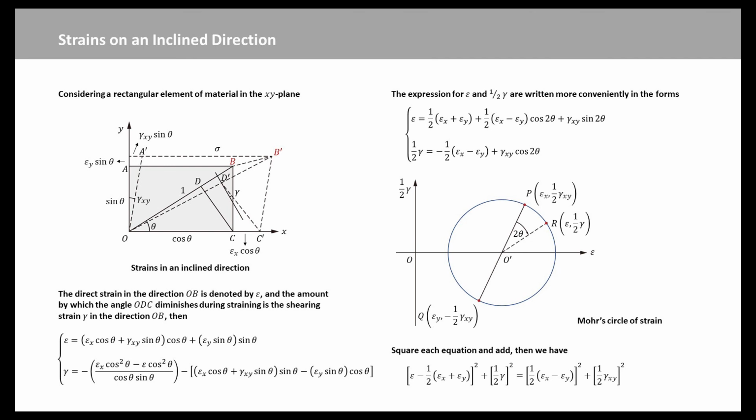An important feature of the strain analysis is that we have not assumed that the strains are elastic. We have taken them to be small. However, with this limitation, Mohr circle of strain is applicable to both elastic and inelastic problems.